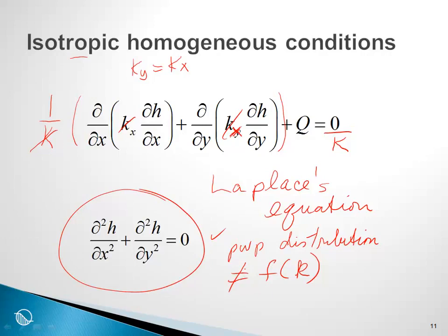If we are interested in quantities of flow, then clearly we need to know the conductivity quite accurately. But if we are only interested in pore pressure distribution, then any rough estimate of the conductivity is likely more than adequate.